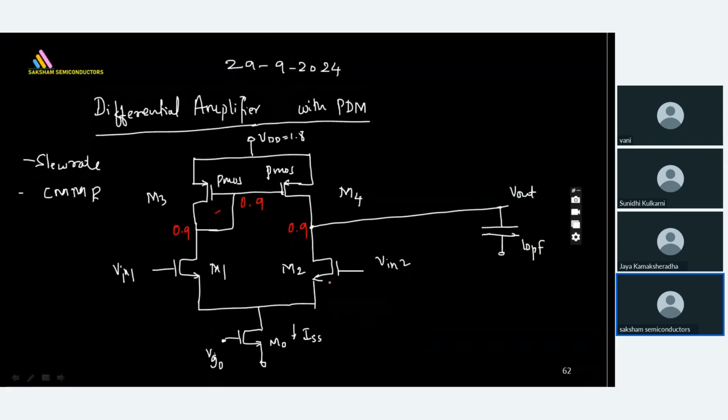Okay, so these are the voltages that are getting divided. Because it is exactly divided between the VDD and the ground, 0.9 volts will come out here. Now between here and here, this MOSFET is there, so that means 0.45 will be divided over here. That's how I'm going to consider this entire thing, so these are the voltages that I have already said.